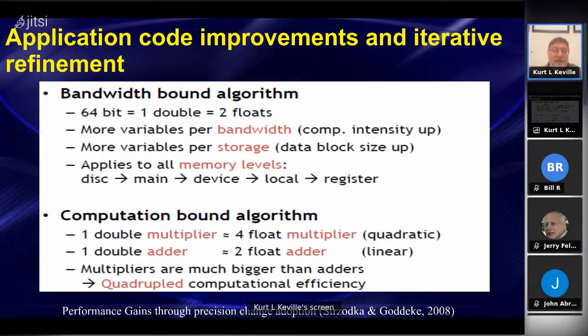There's plenty of people doing AI and ML in integer, and I don't know if you can do 1 bit, but they're probably going to try it. So int 8 is where it is now. Is that right? Yeah. There are a bunch of things using that, and then I think float 8 is also being looked at, where you just have 1 bit for the exponent and then everything else is mantissa, because for a lot of these things the whole range is between -1 and +1, so they don't need a bunch of exponent bits.